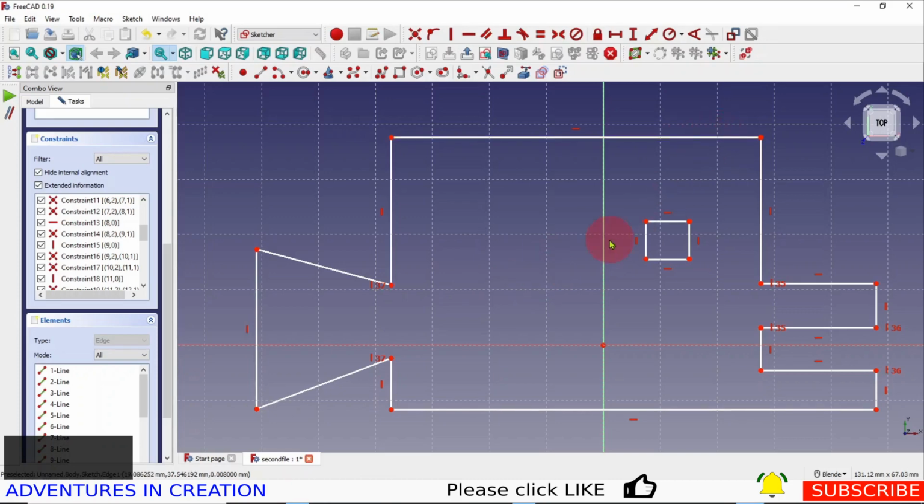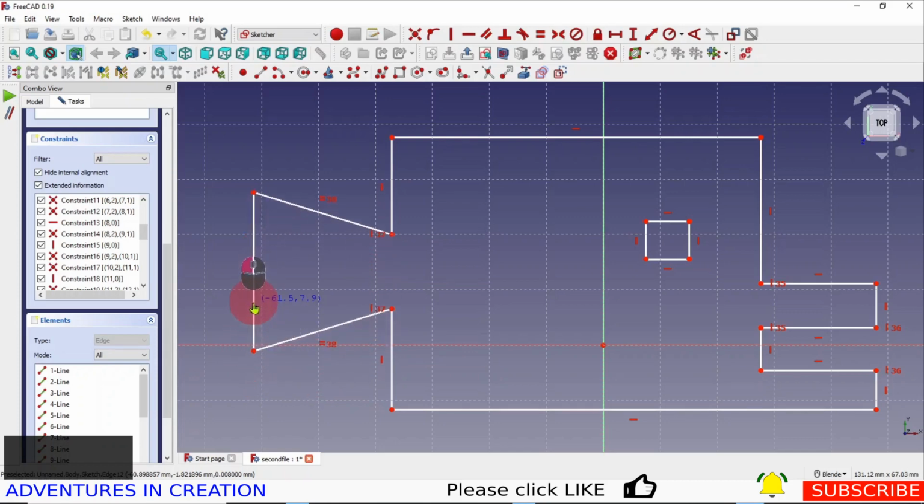So let's take a look at setting up other geometry here. We have, these are angles. They should be the same. So I can click that line, and tell them that they are equal. And now those lines are the same. So if I change things, those lines should change in the same manner.